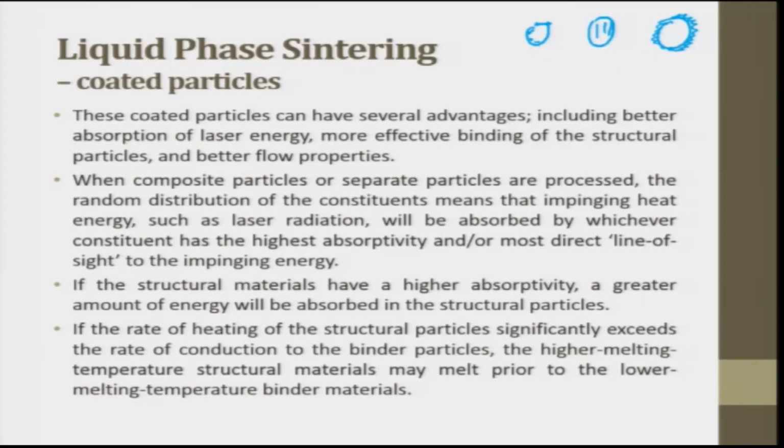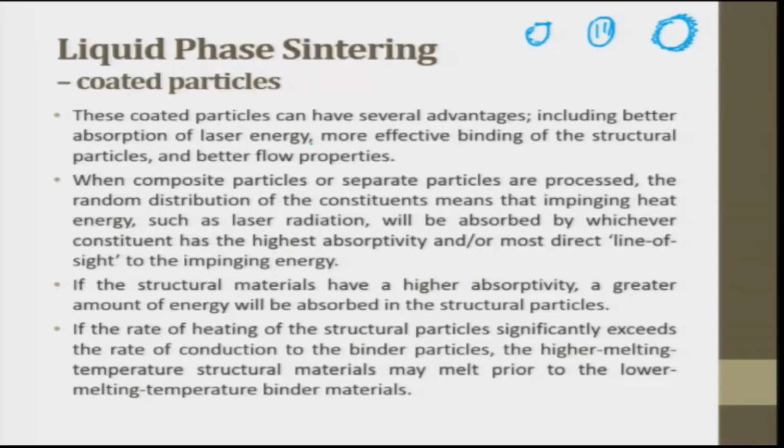So, you can have nickel of X percentage absorption, copper will not have the same percentage, cobalt can have higher, tungsten carbide which is used here need not have anything. So, depending on the absorption property of the metal or the particle whatever we use, we can use it for the advantage of liquid phase sintering. So, including better absorption of laser energy, more effective binding of structural particles and better flow properties.